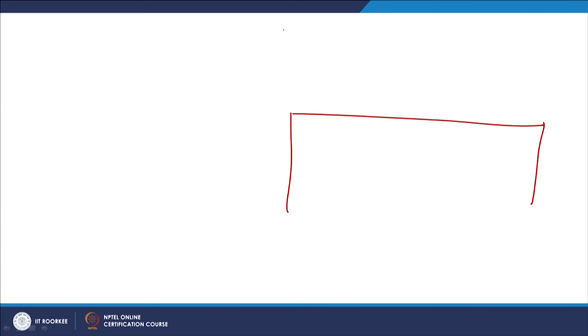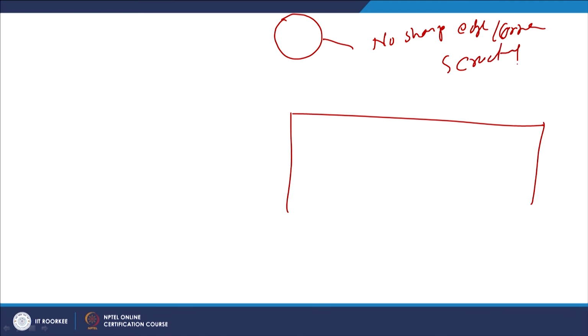So, this is what we can see as far as the particle size is concerned. The shape of the particle is another aspect. If the surface of the workpiece is subjected to impingement by spherical particles, since they have no sharp edges or corners to cause scratching or cutting, this will lead to low erosive wear.